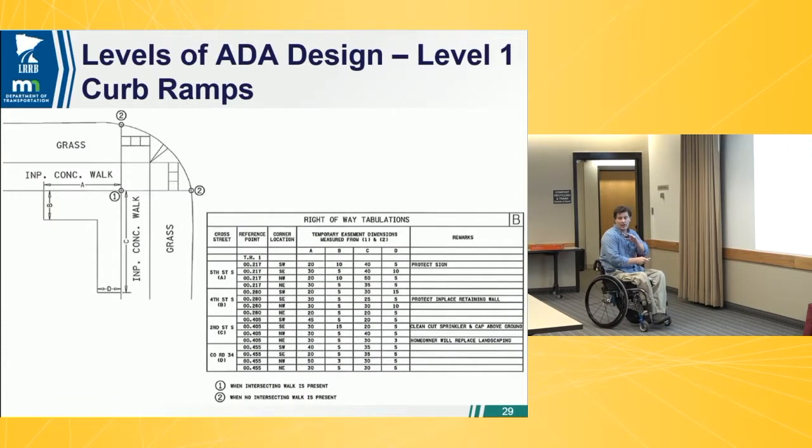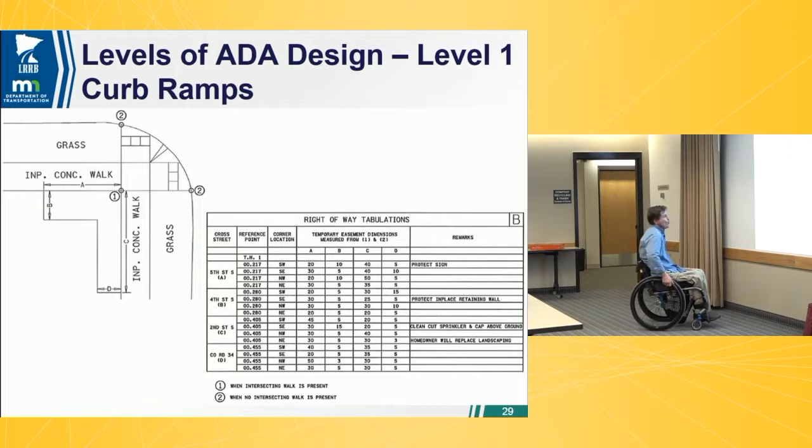Because there are trickier areas that I'm going to get to. But again, our right-of-way folks say, well, we need a plan sheet to show where your right-of-way is, your TEs and everything. So I'm saying, well, no, not really. You can actually do this in a tabular format if you want. And this is just a way of me proving you didn't have to do a plan sheet. But this is actually how construction limits are done for curb ramps as well. We're not cutting cross sections on curb ramps. We're just finding where those removal limits are. Maybe say distance A, 15 feet back. Distance B, maybe 5 foot off in a regular area. If it's a steep cut area, it might be 10 or 15 feet. But you're doing these approximations for easements. Like I said, you're not doing cross sections.